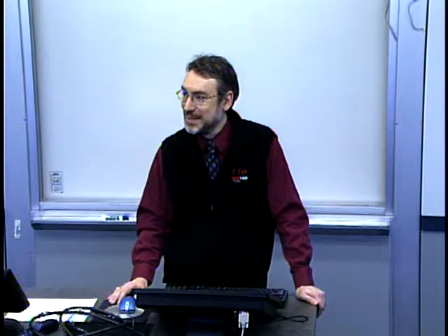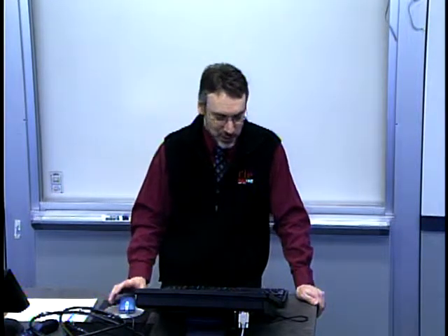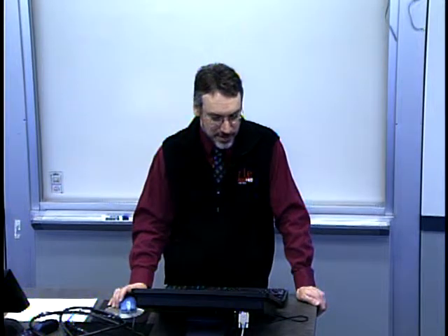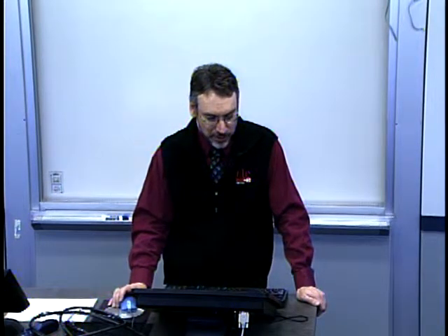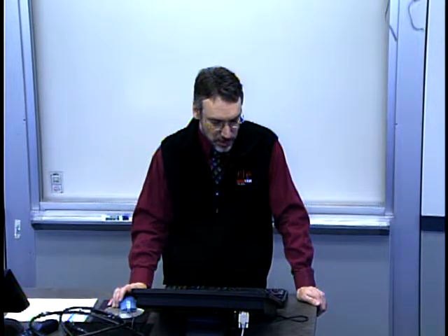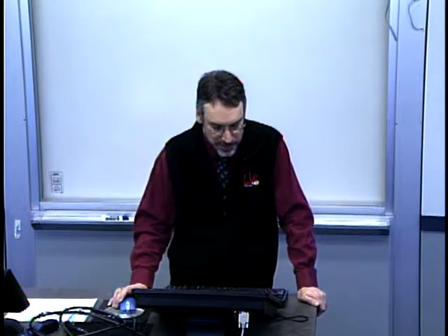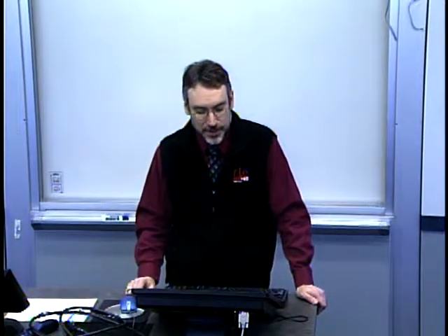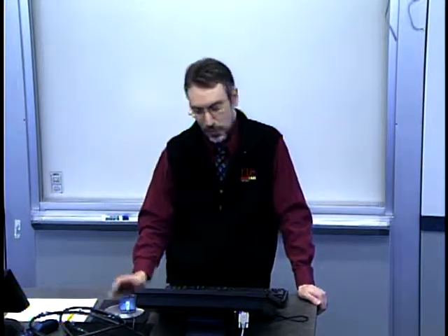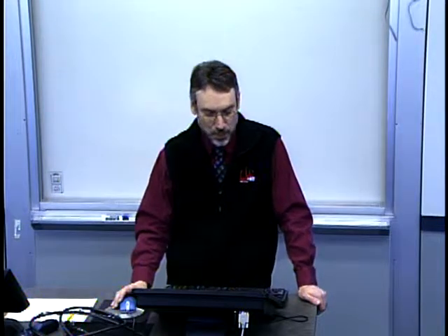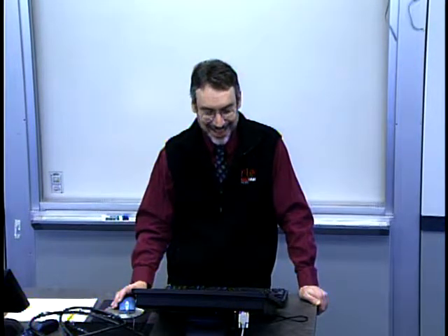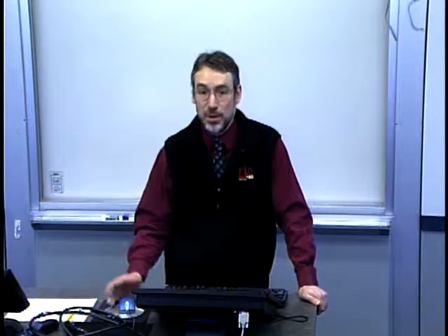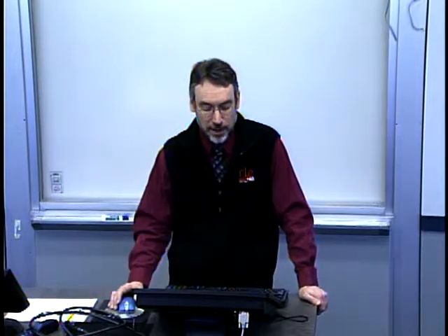Is it uniform? Not especially, although you always have to be really careful looking because, on any kind of plot, you want to really look at the spread. I mean, here it's kind of magnified because here's 0.7 inches, and we're down to about 0.697 up to 0.702, say. So that's not full scale, right? But if we zoom in around whatever nominal is, and in fact it's not even clear what the target dimension was. I might guess that it was 0.7 inches because that's a nice round number, but who knows, right? So it's definitely not uniform.